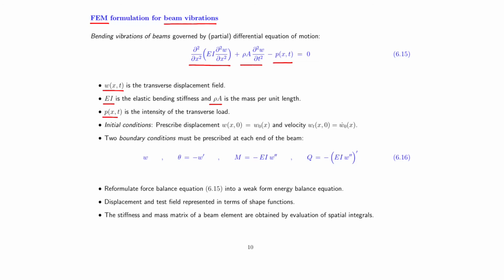some loading. Of course, we need initial conditions to activate our vibrations, and we also need boundary conditions, and because we have a fourth order derivative, then we will, in principle, have boundary conditions of 4 different types, but for the finite element formulation, we will only use the kinematic boundary conditions. Either we have a condition saying that we have no displacement, like we had for the cable, but additionally, we will also have the possibility of no rotation, whereby theta, the nodal rotation, is prohibited.